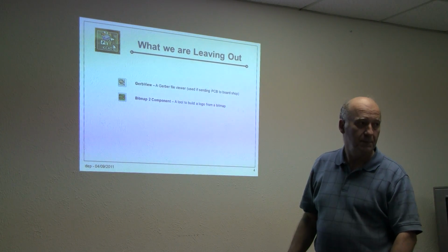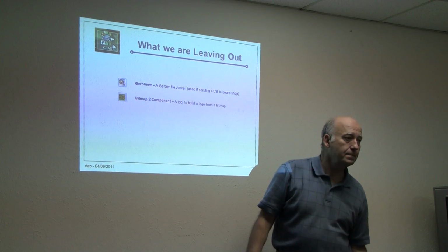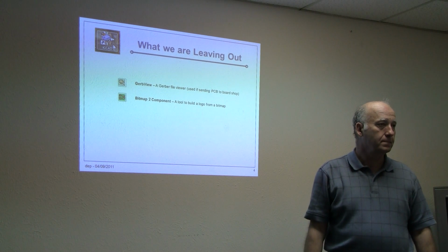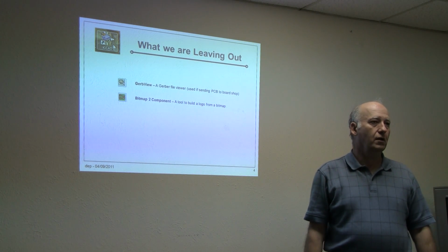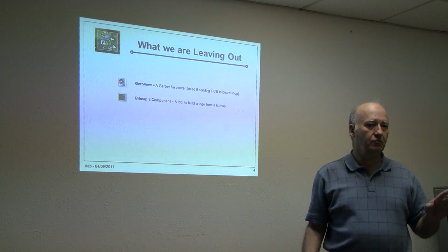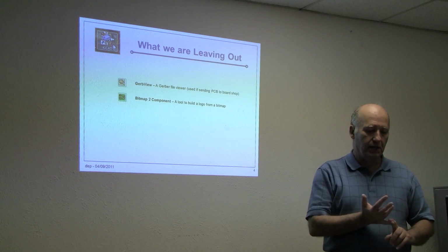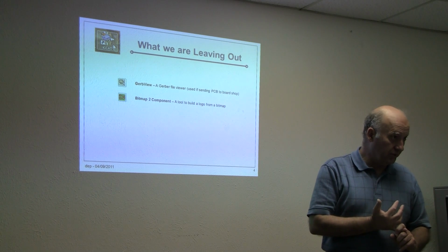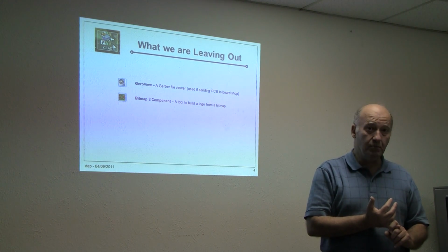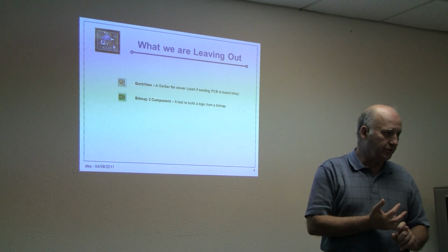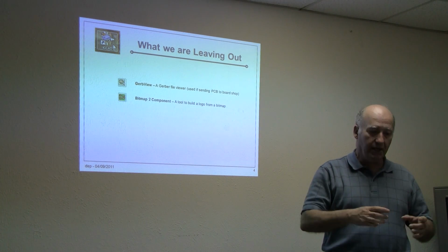Okay? One more question. Sure. Are you going to cover creation of new schematic symbols and PCB footprints? That's one of the nice things about KiCAD, it has a component editor, which is the symbol that you put on a schematic, and it also has a footprint editor, with which you can create the footprint.